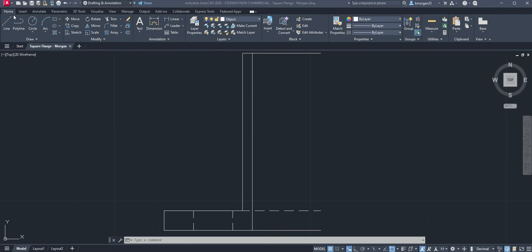All right, then we are going to go to Home and then the Modify panel. Of course, we will use this Mirror command. Just click on it, and it will go into the mirror mode. Sometimes your mouse can be stubborn, so make sure that you click on it. Sometimes you might go to a different window. When you come back, your cursor will look like a little arrow. All you have to do is click on the canvas and you will go back into the last mode. So my mode is right now in the mirror mode.